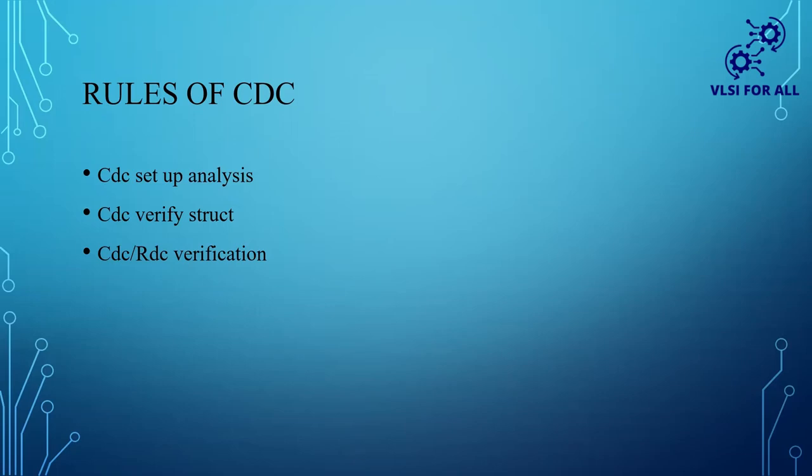In CDC setup analysis, what things will be going on? The tool will check the clocks, whether all the clocks are present or not, whether all the resets are present or not, and whether there are any file compiling issues. All of these are checked under the CDC setup analysis. It checks the clock, the reset, and all the files, whether the library files are present or not. It also checks for compiling issues.